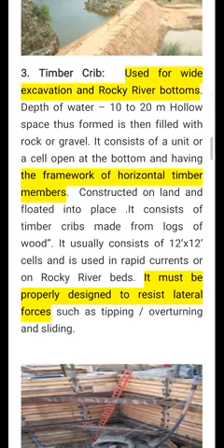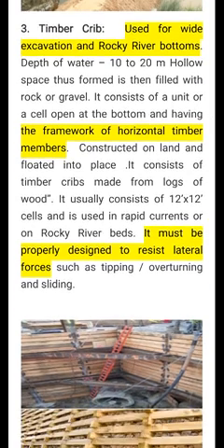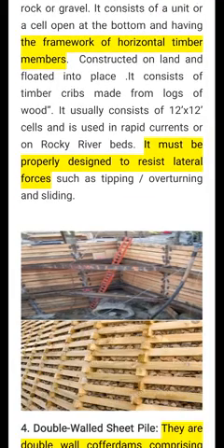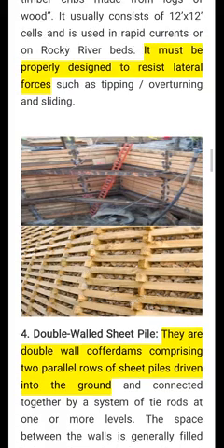Now, timber crib. A timber crib is used for a wide excavation and a rocky river bottom. This is the formwork formed by timber members, parts of timbers, and it must be properly designed to resist the lateral forces. You can see the timbers. These are timber blocks, timber sills, which in the first figure are braced. In the second figure you can see timber cribs supported by rock filling. That is the timber crib.